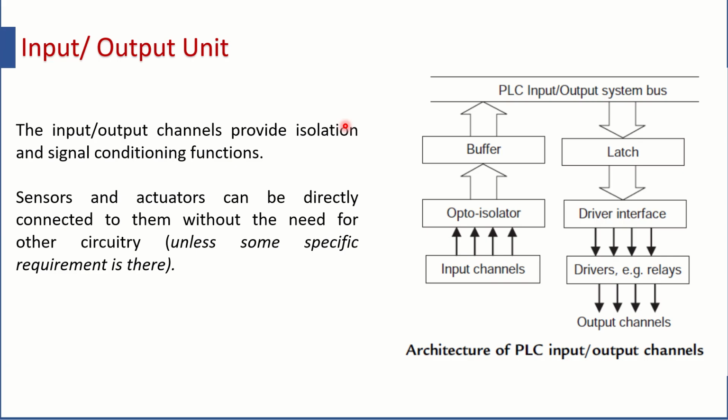So if there is some surge of voltage coming through the switch accidentally, then the switch will be burnt, and at the same time you are connecting the switch directly to the input port of the PLC, that will also be burnt. So your PLC will be damaged, your entire input card will be damaged for the PLC, which will cost you a lot. Therefore, safety measures have already been taken inside the PLC in the form of isolations, and after that you are allowed to connect your device to the PLC.